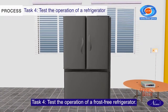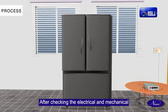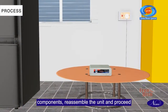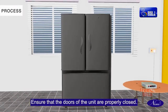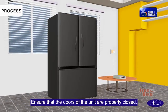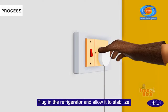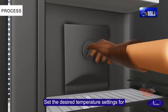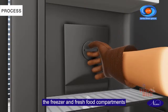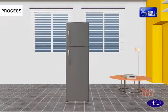Task 4. Test the operation of a frost-free refrigerator. After checking the electrical and mechanical components, reassemble the unit and proceed to test its performance. Ensure that the doors of the unit are properly closed. Plug in the refrigerator and allow it to stabilize. Set the desired temperature settings for the freezer and fresh food compartments as per the refrigerator's manual recommendations.